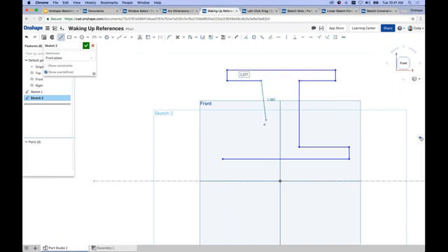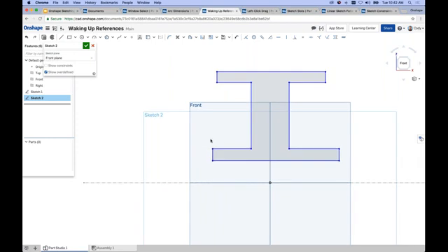If I left click, let's say that I'm bringing down this line on this side, and what I want is a constraint to that point over there on the right. But you can see there's no reference that's been pointed out there. All I need to do is move my cursor over that point, and it will wake up that reference, right? And now I can constrain my line to the point, making them equal, without having to come back and manually do that later. Same goes for this point. Move my cursor. It does not reference this point, so I will move my cursor over it, wake it up, and there is my finished sketch profile.